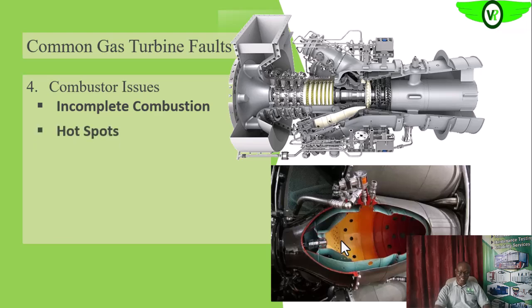So it is possible that the combustor too can develop hot spots. If we have deposits on them, those spots could develop. Where we have those deposits, those spots can generate excessive heat that is higher than the surroundings, and that excessive heat can damage the material, the component of the combustor at that particular point, which can lead to deterioration and eventual failure at that point.